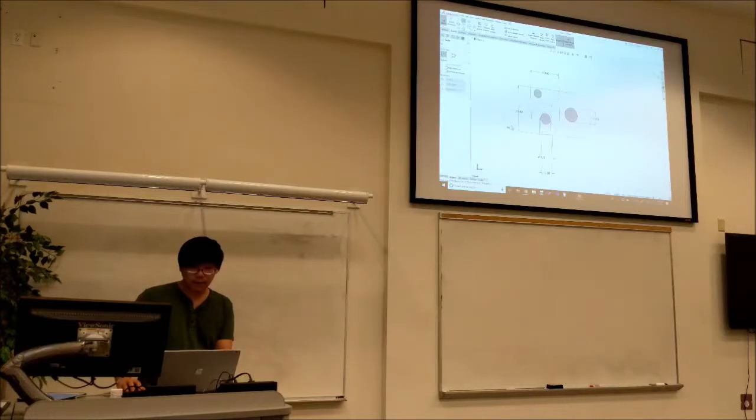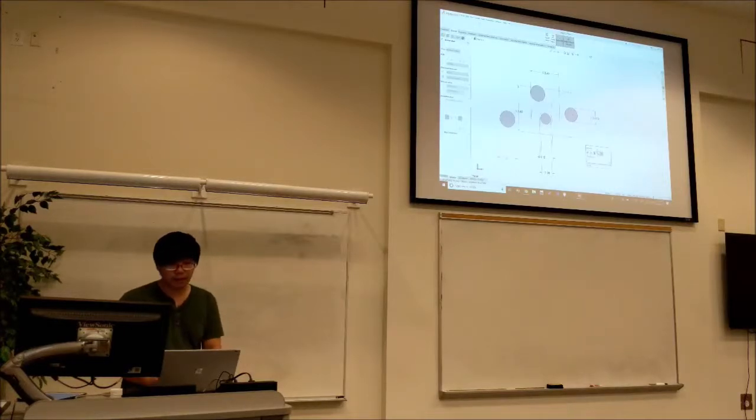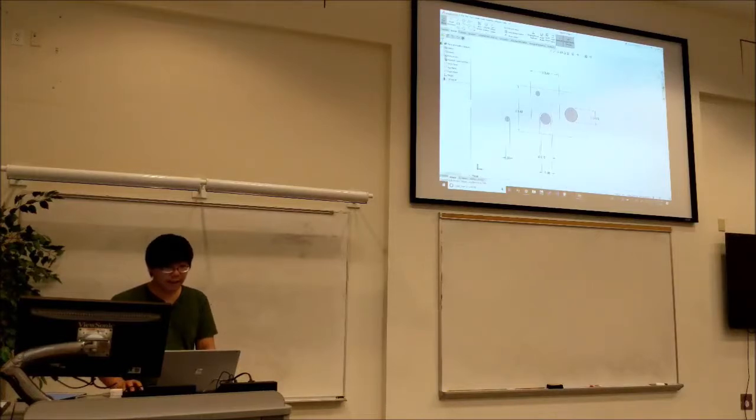So we have two 775 Pros, so we need two pinions. So they're going to be the same size, obviously, so we can make them equal. And then basically the pinion that Vex sells is a 12-tooth pinion, so we can do 12 divided by 32 plus 0.003. And then this is the output pinion of your 775 Pro. So you can make both of these tangent to the gear that it's driving. And we can also make a construction geometry again, because it's not part of the final part.